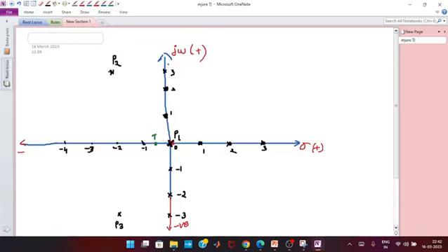Always the root locus branch starts at open loop poles, right? So here the poles, and it ends at zeros, but unfortunately for this problem there is no zero, so it may terminate at the point minus infinity. So the root locus branch will be like this. So this is our root locus branch starting and ending point. This is what the second step indicates.